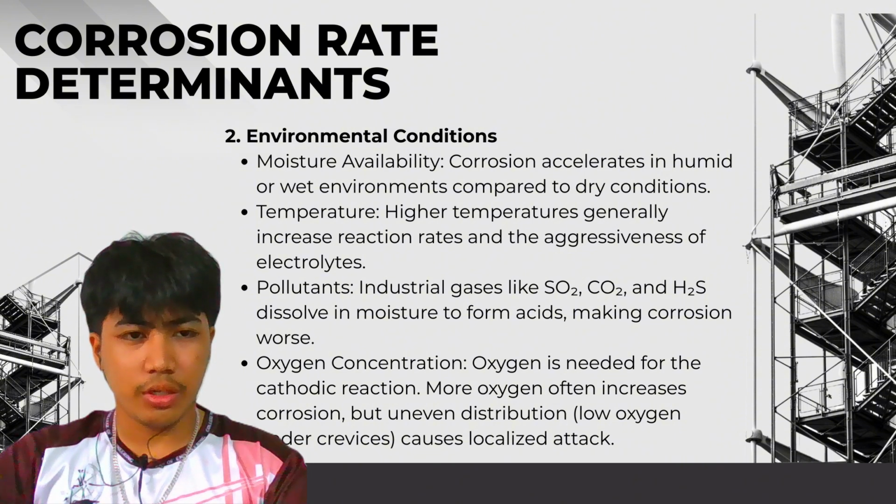Oxygen concentration. Oxygen is needed for the cathodic reaction. More oxygen often increases corrosion, but uneven distribution, low oxygen under deposits, causes localized attack.